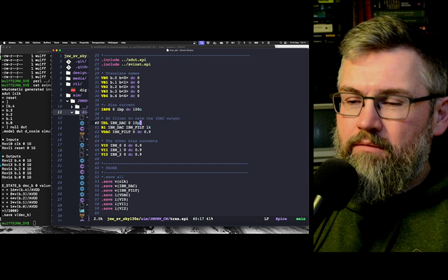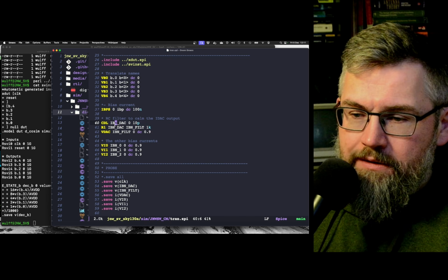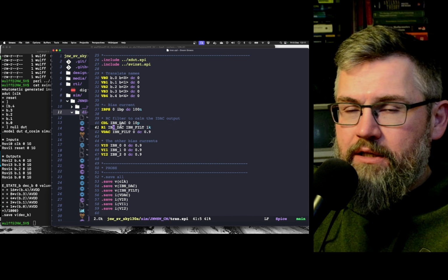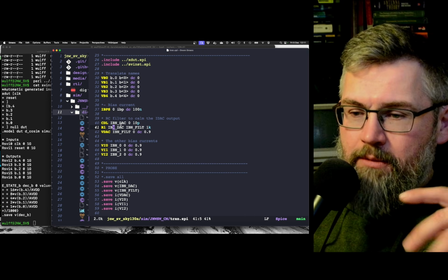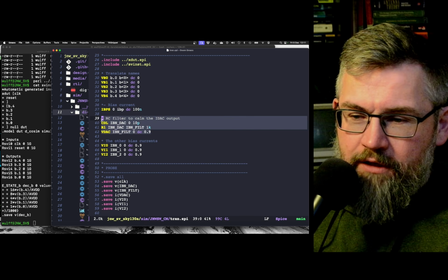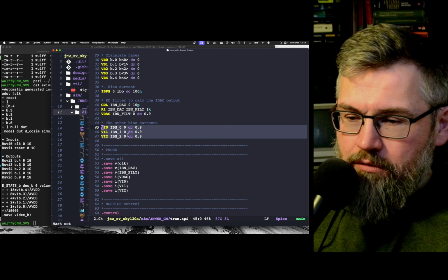Now, this next section is just an RC filter on the DAC output voltage, because when the binary DAC switches, there will be charge injection and glitches and so on. And I just don't want to see that in my simulator. So this is a small cheat. And then we have the other bias currents. I set the voltage so I'm able to measure it.